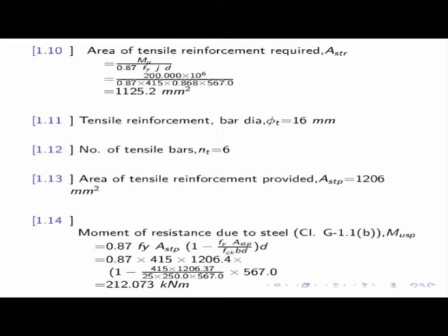And as I told you yesterday, this is an under-reinforced section. That means we allow the steel to fail, because then we get a warning. But if concrete fails first, we will not get a warning, because it is a brittle material; it will fail immediately without giving any warning. So this is the way we do the design, and this is how we design this particular problem.